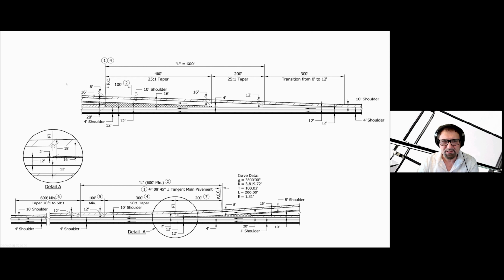That's about 900 feet just to arrive at the point where we will depart the same formation for the road. And then we need plus additional widening or some curves to exit from the main line. So using the standard exit ramp, I will apply that and extend this 25 to 1 taper for a further 500 or 600 feet.